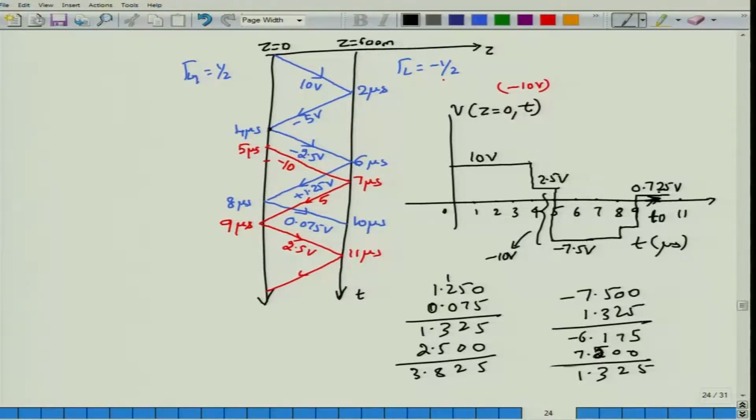Okay, so in one case you had multiple pulses between the transmission line propagating and coming back, and in this case you have the transcending end pulse that is completely distorted because of these transmission line effects. Okay, you did not expect this negative big large pulse, but unfortunately that is what you are going to get. Okay, before we close the discussion of pulse propagation and we go to the other module, I have an important kind of a setup that I would like to consider.